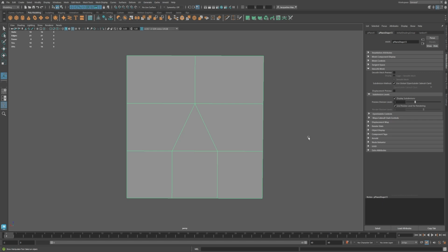Triangles actually don't pose any technical issues when we're talking about smoothed mesh. When we have a triangle, once it goes through the smoothing process, it's going to get subdivisions that turn that triangle into a collection of three quads. So we're fine here. And if we increase the subdivision level, you'll see that it just continues to flow that topology through those subdivisions so we continue to have quads. So the triangle is going to deform perfectly fine, technically.